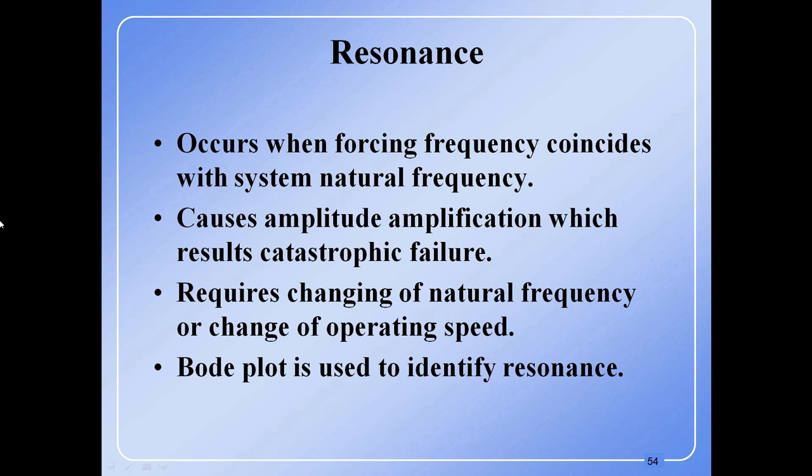Resonance. When will resonance occur? It occurs when the forcing frequency coincides with the system natural frequency. When it occurs, it causes amplitude amplification, which can result in catastrophic failure. It requires changing the natural frequency or changing the operating speed. A Bode plot is used to identify resonance.